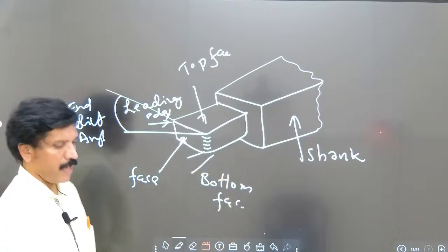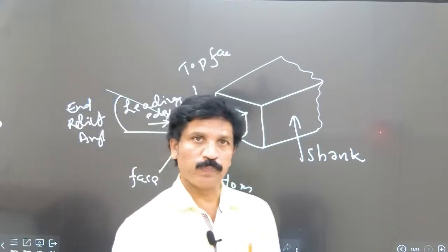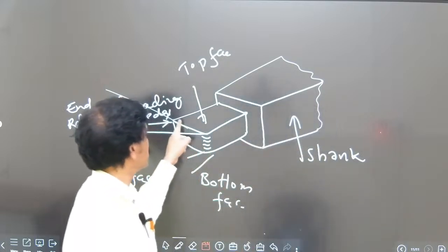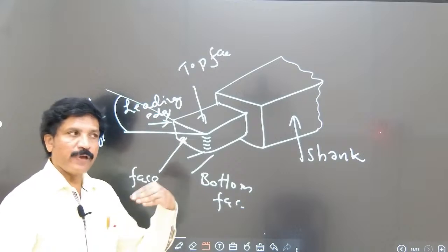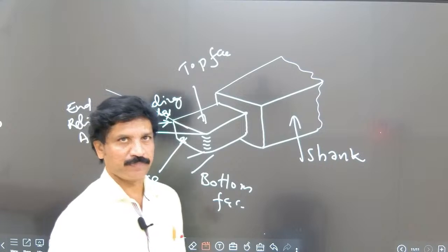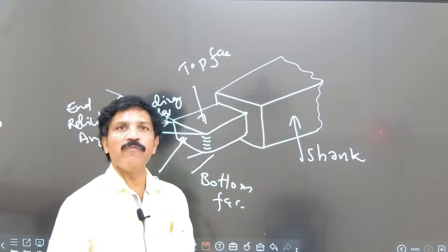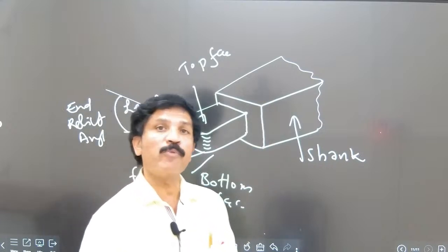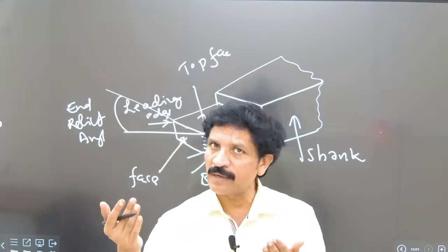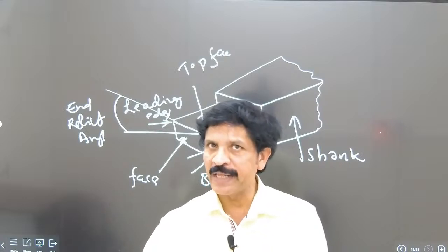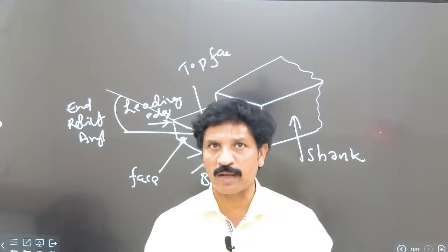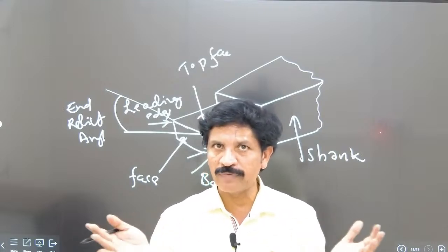So here, as per the cost of the tool, where the tool is interacting onto the surface, it should be the hardest. And here is where we accommodate the tool, on the tool post. That space, that material, is not interacting with the workpiece, so it need not be that strong. That's why it is a combination of different materials.